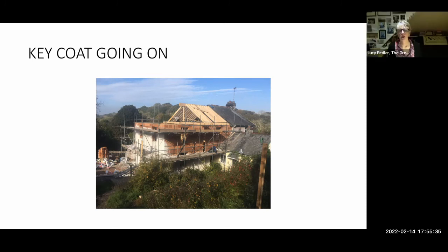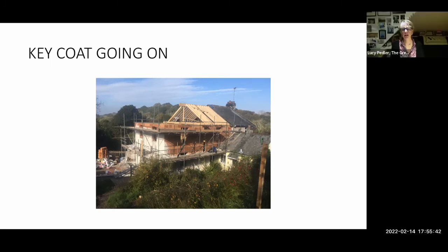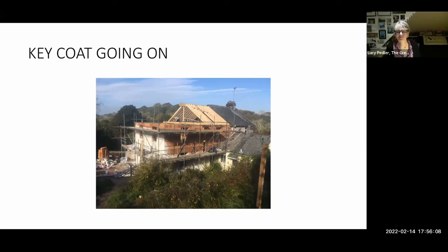Okay. You were very clear about getting that first course really right, and Terry said he's used a laser to level the first course. Have you ever employed that method? Well, what we did was we lasered a former around with the OSB, so it meant you've got something solid to place the block onto. It worked really nicely, it took out 2 degrees of freedom when you're laying that block.